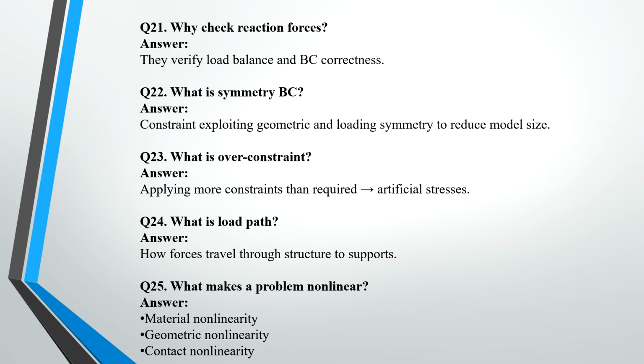Why check the reaction force? Why do we have to check the reaction force? They verify the load balance and the BC correctness. Before going to any other analysis, first we have to check the reaction forces just to check whether we are getting correct results, whether we have applied the correct BCs, and whether the load is actually balancing. So before anything else, we have to do this reaction force check.